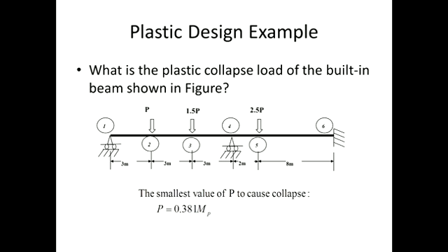Like if you look at a beam which is under uniformly distributed load, for example, you are not going to have plastic hinges forming at every point. The system is going to pick the weakest cross section, and that's where the failure is going to occur. That's a good question.